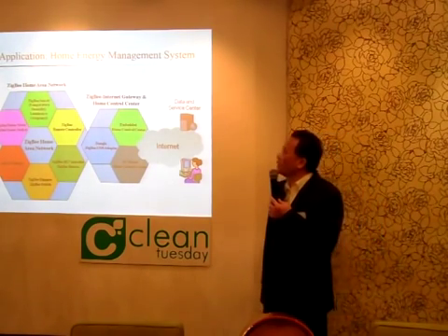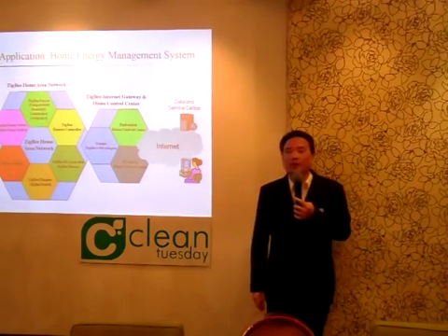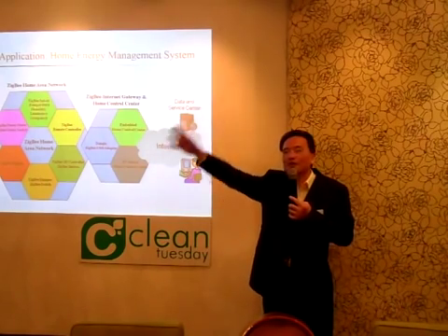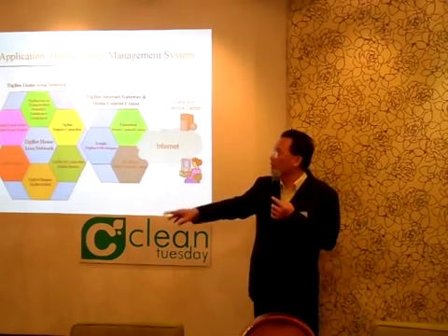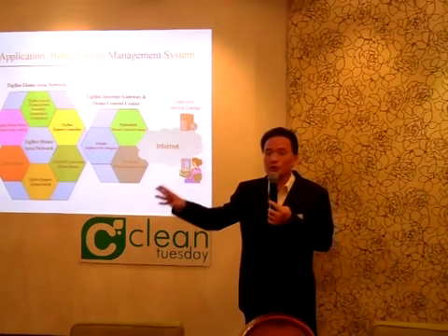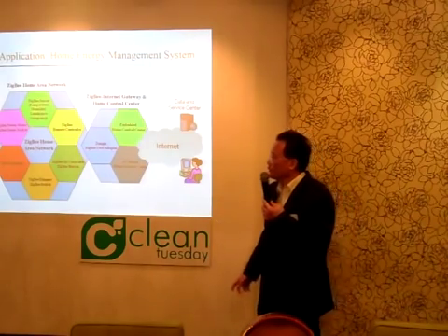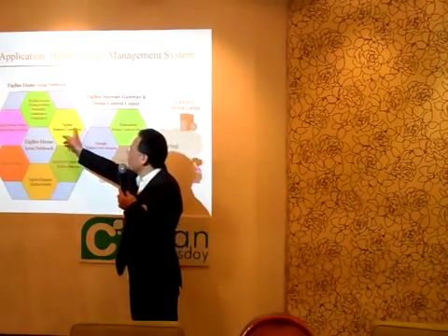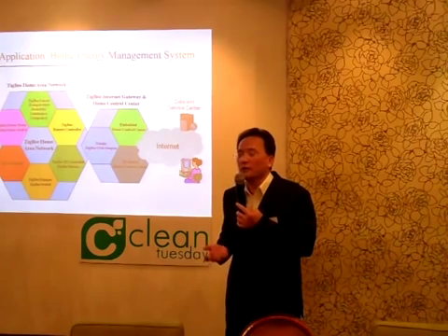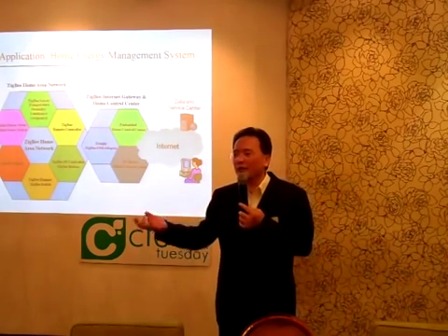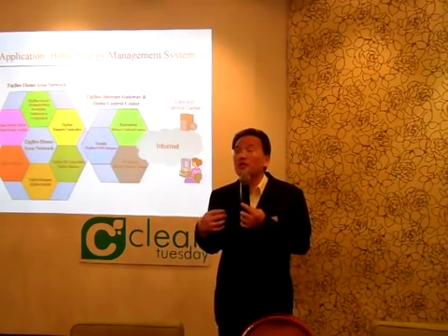All right, so finally I want to talk about an application that we have developed. This application is called the Home Energy Management System. The smart grid consists of the power generators, the distribution network, and the consumers, and this particular application is at the consumer. The idea is to monitor the usage of electricity at the home. We develop a system based on ZigBee communication technology. ZigBee is a wireless communication technology, not very different from the Wi-Fi technology that you're familiar with, but it is a shorter range and it uses less energy.